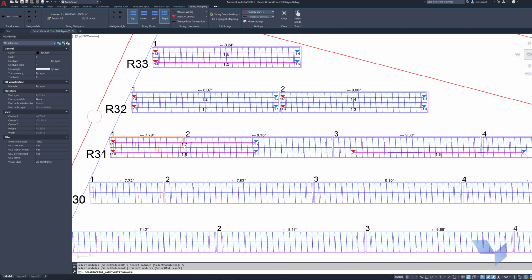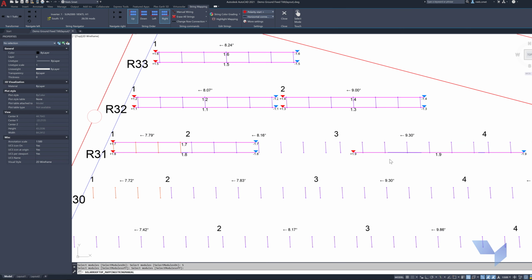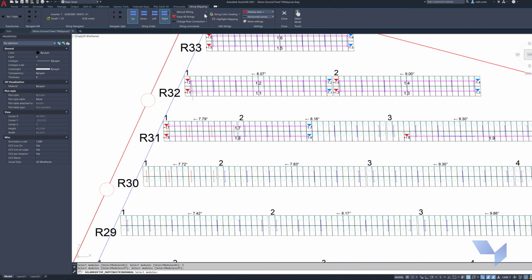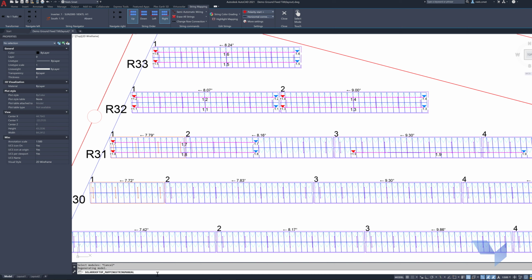When you want to connect modules that are not grouped together and you want to draw the interconnection yourself, you can use Manual Interconnection option. After selecting Semi-Automatic Wiring option, select Modules option. Click on it in the command line or right mouse click menu.